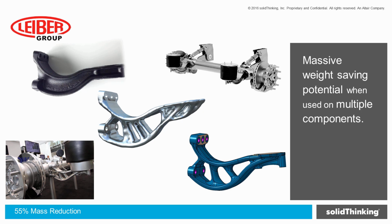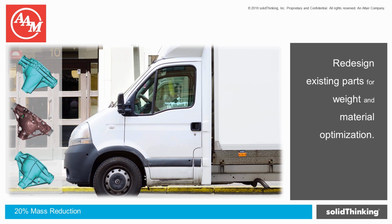It can be used to redesign existing parts, like you see here from Liebherr Group. They have a bracket that is for a spring, an air spring on a heavy-duty truck. So they have 3 axles. Each axle has 2 of these air springs. They were able to take the existing cast design, redesign it, and reduce the mass by 55% with the same performance. We see this a lot in vehicles, and a lot of what we're targeting here is mass reduction at the same performance. Mass reduction oftentimes means less material cost.